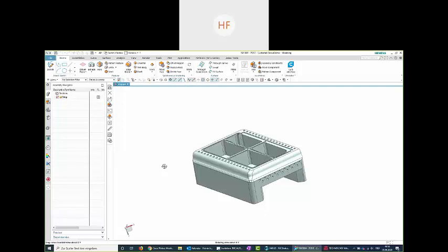For this, I will also use another manufacturing set. I'm just making a right click, insert. I want to insert a geometry as I, as a human being, have recognized a geometry in here. In my templates, I have the possibility to select a freeform. And then here it also already tells me to select all faces for 3-axis copy milling. Okay, so let's do that.